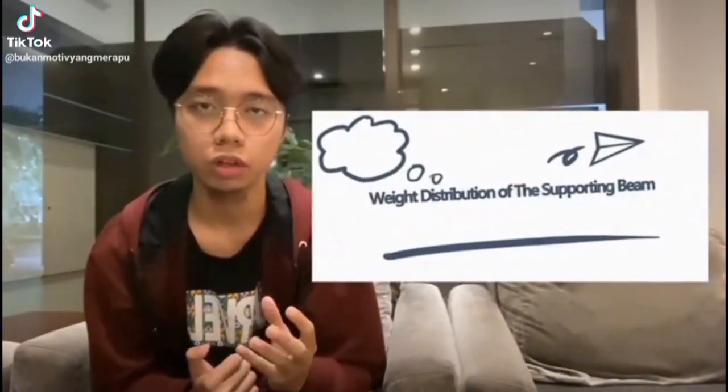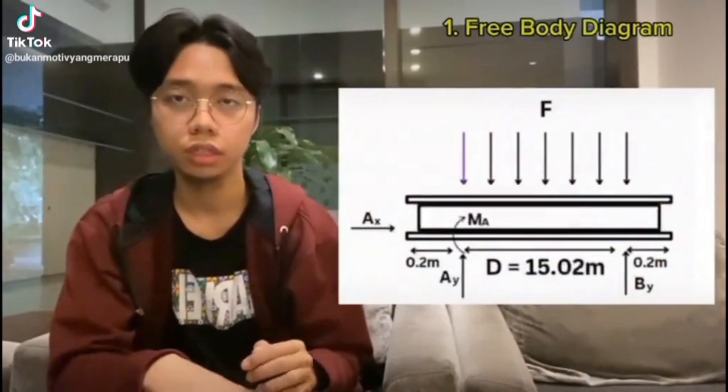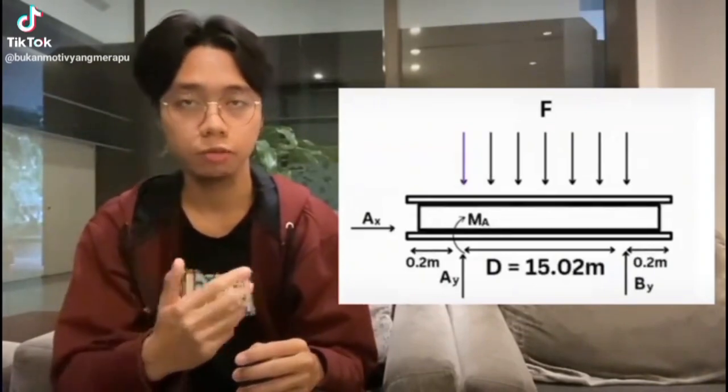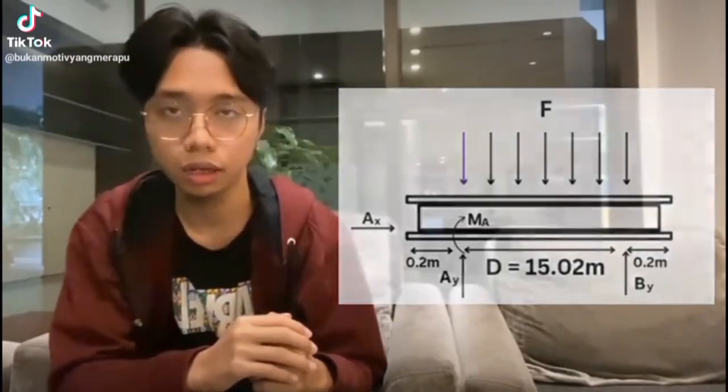Now I will present how to get the weight distribution of the beam of the cylindrical water tank. The first step is to draw the free body diagram to give us a clear visual of all forces that are available. So as you can see on my right, this is the free body diagram. A is a pin, B is a roller, F is the distributed load, D is the length of the cylindrical water tank. For your information, our group increased the volume by 15%.